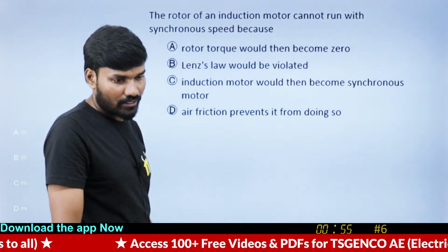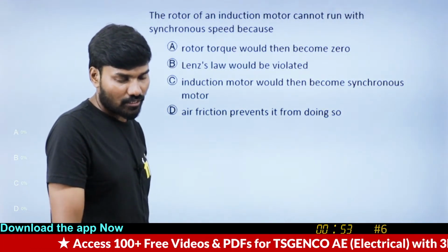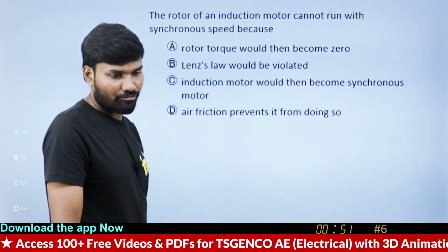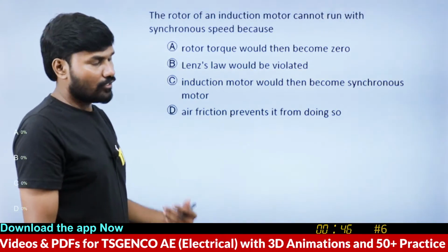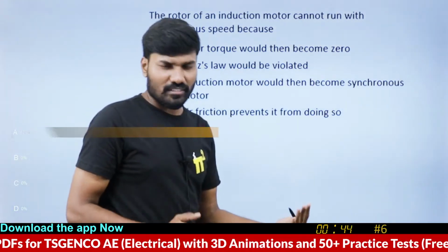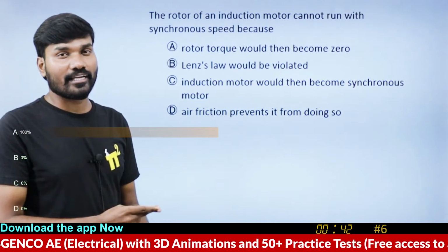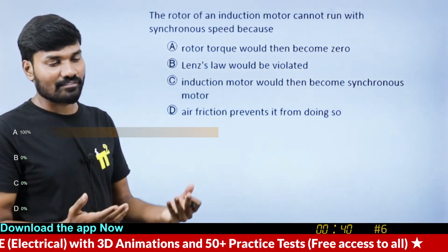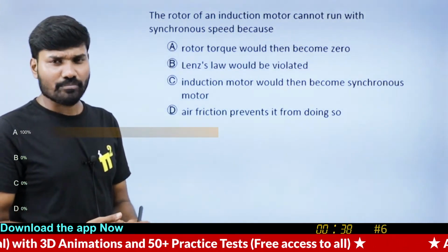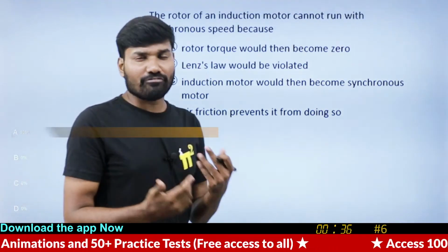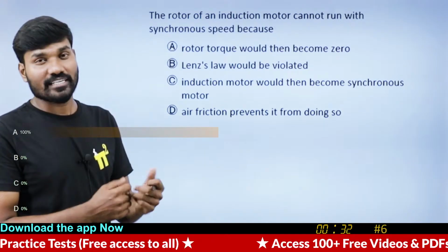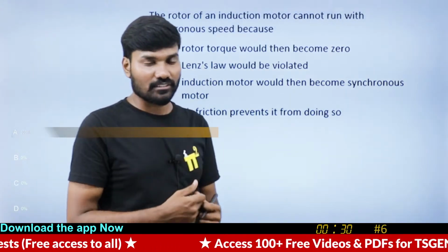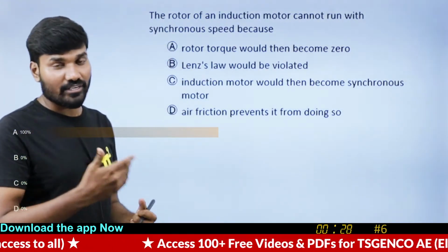Is an inverted induction motor rotating opposite to the RMF? Inverted induction motor, it's basically braking mode. The same induction motor under braking mode. If you are naming it an inverted induction motor, it's okay, but it's a braking mode. In the braking mode, definitely it has to rotate in the opposite direction. Opposite direction means both directions are opposite, hence the slip is higher.